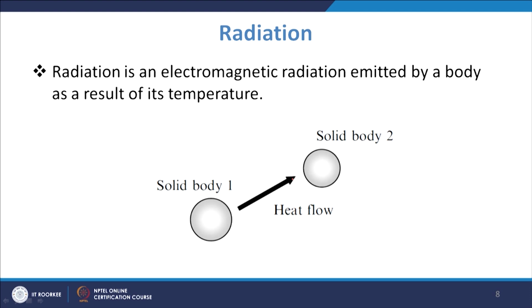Now, in the case of the Tundish, you have many surfaces which are open. You have the top surface of the Tundish, where you have the slag layer, which is also at higher temperature. There will be heat transfer from that surface, because it is exposed to the atmosphere, and the slag is in touch with hot metal and is at very high temperature. So they will be losing heat to the surroundings by the radiation mechanism. Here you have a similar process, but the exponent on the temperature is different, given by the Stefan-Boltzmann law. That we will see.